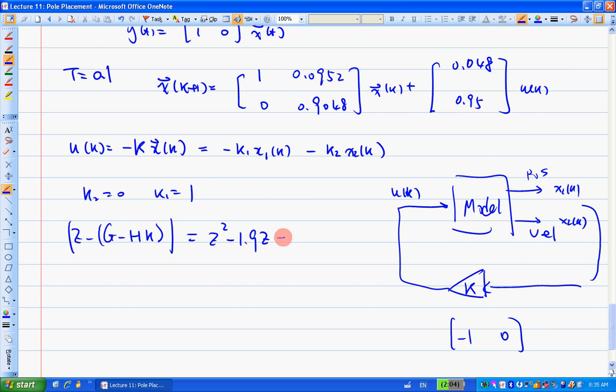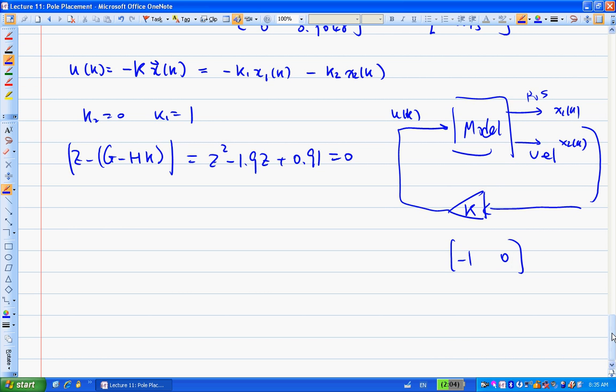In this case, it's this. So this is kind of arbitrary here. We don't even know what pole we placed, where we placed here, right? Because we just basically pick two values, k1, k2. But we know that once you pick a k1, k2, you are replacing the original pole, placing the pole at a new location. So where's the new location of the pole? It's the solution of this characteristic equation of the closed loop, right?